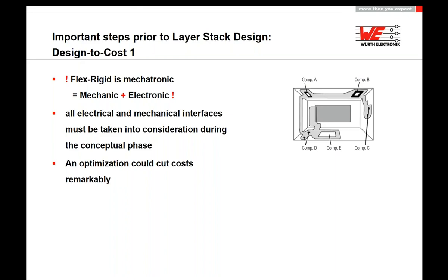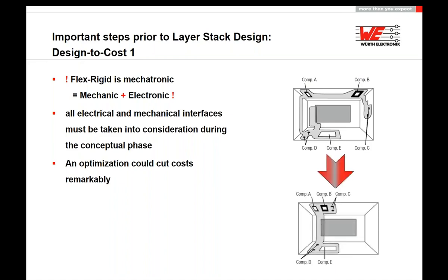And finally, you have to document this. On the right side of this slide, you can see some possibilities for how to do this. And then point 4, you will have to run a board planning mode to teach the system where the flexible and the rigid areas should be.